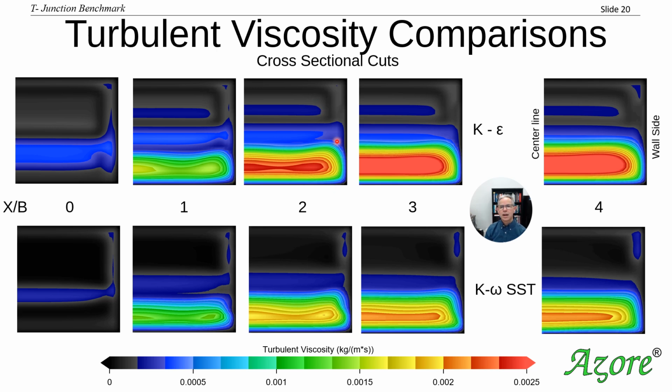The other thing that is kind of interesting to look at here is, our turbulent viscosity in the center of the duct is larger because there's nothing limiting the rotational motion of these whirls or eddies. But as you approach the wall of the duct, you'll notice that the turbulent viscosity begins to drop very rapidly. And that makes a certain amount of sense because now these whirls, these tumbling flows, are striking the wall and they're dying out. And we see that happen in our scalar field, our turbulent viscosity that's trying to represent this behavior. So that all makes a certain amount of sense.